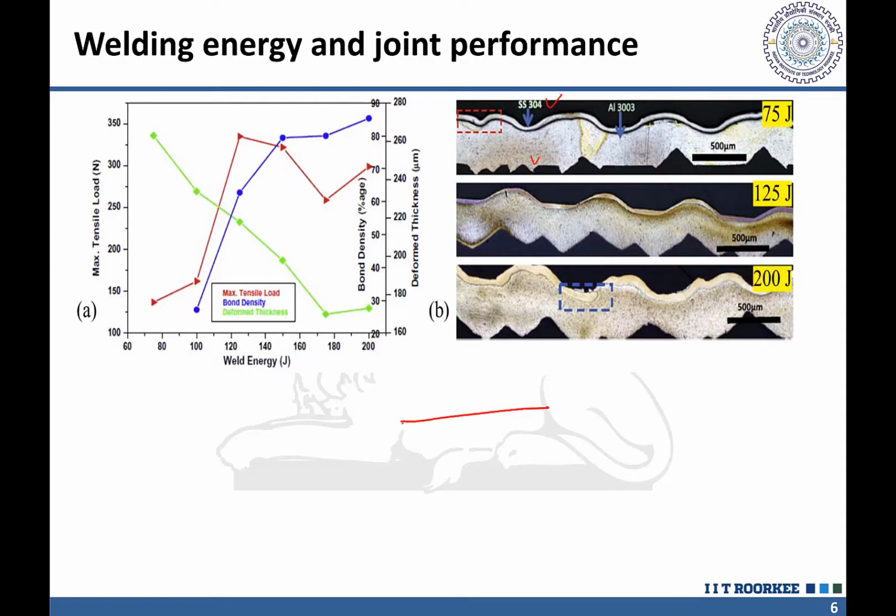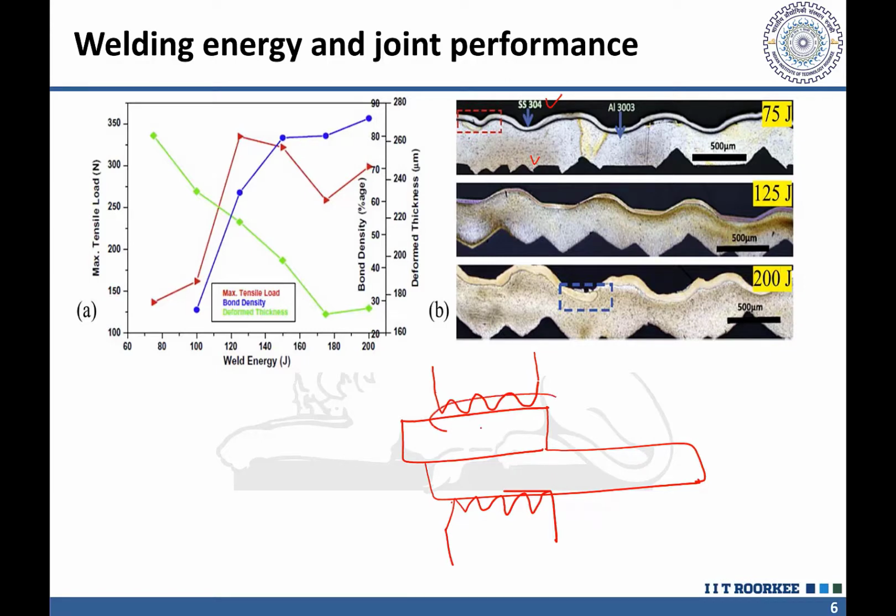So what we do, we take the two components like this, okay, and we apply the sonotrode. The sonotrode has a very typical geometry at the surface through which these are applied, so that you can apply very intense vibration in a localized manner wherever you want to develop a joint. This will be increasing the localized pressure at the surface of the workpiece, on both sides.